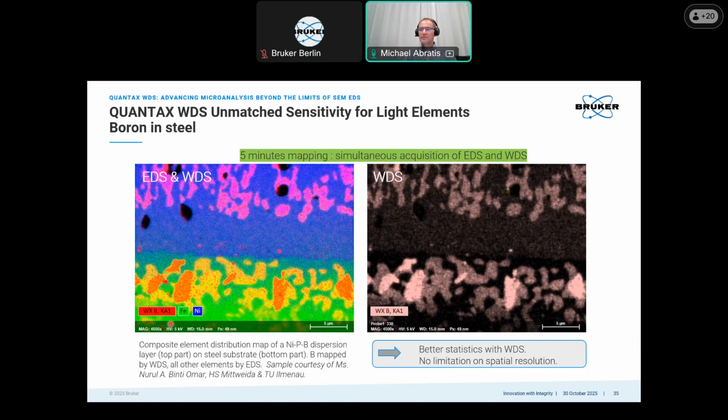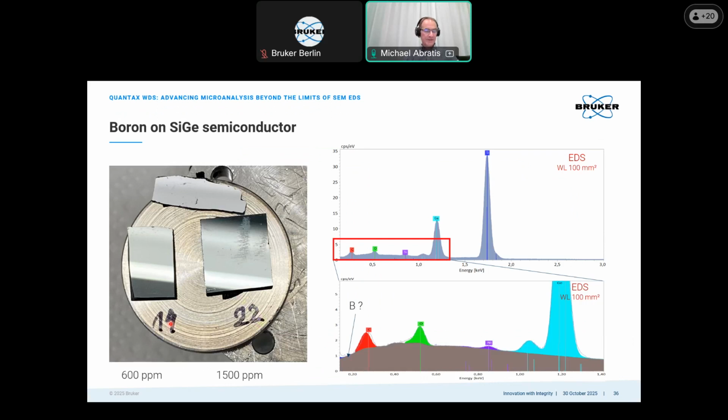Yeah, one example with a conventional EDS, this is certainly a bit unfair for the comparison. For the light elements, we would clearly choose a windowless EDS because there is no absorption in the window. So a windowless detector would do the mapping faster and also give a nice image after 5 minutes. But the problem where the windowless detector gets stuck